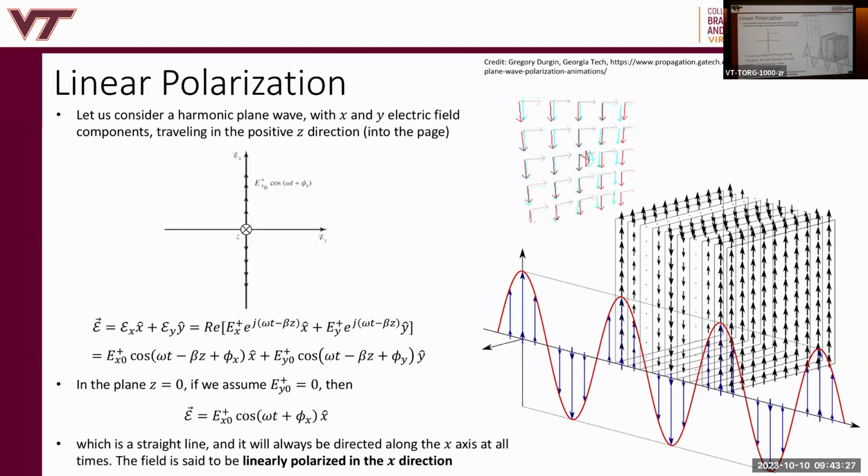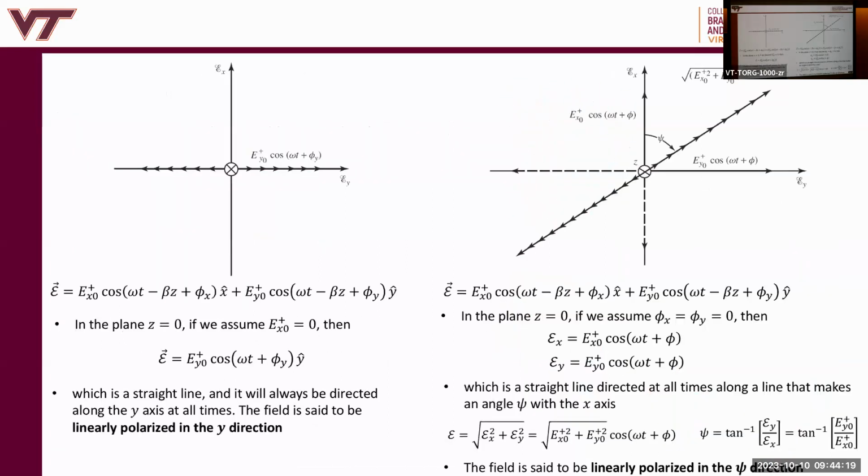Polarization is very important to understand. If you design any communication systems, if you design anything with antennas or point-to-point links, or even scattering problems, you could have polarimetric radar, where you try to measure rainfall or something, and you send an electromagnetic wave to it. And because of the raindrop being spheroidal, it's not a perfect sphere, then you want to measure the response due to both polarizations. So you need to know the polarization of an electromagnetic wave. You need to design your antenna to launch that electromagnetic wave's polarization. And you need to know the properties of your scatterer. Maybe they rotate polarization, or maybe they take one polarization and send back two, right? So there's information in the polarization. You can also pack information in communication systems on different polarizations since they are orthogonal.